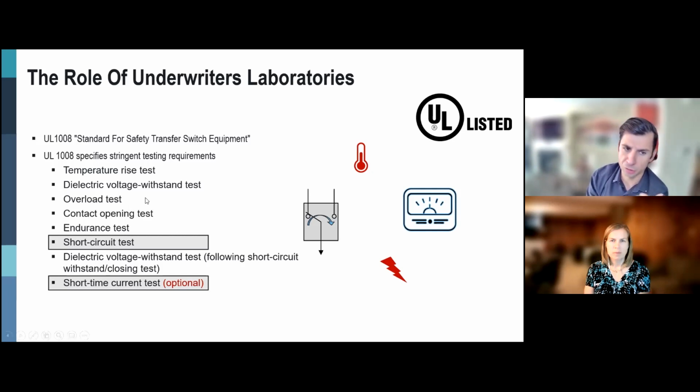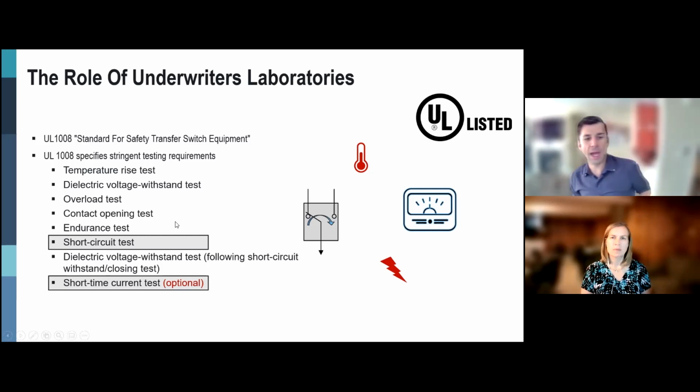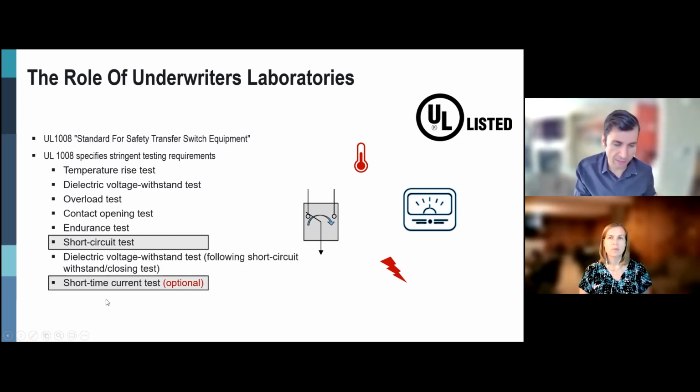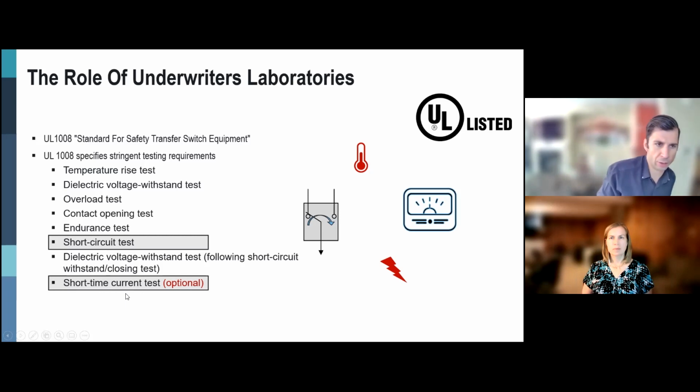They specify a temperature rise test, dielectric voltage withstand test, an overload test, and an endurance test. And then you are required to have a short circuit test, and then they do a dielectric voltage test after that. The standard also has an optional test, called the short time current test. So we'll talk about that here shortly.